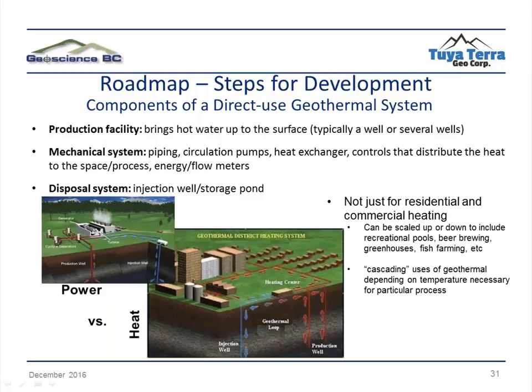And then you've got the disposal system. So where are you disposing that system? For the most part, injection wells are used in order to maintain the pressure of a geothermal resource, for example, and to minimize environmental impacts. You don't want to be necessarily storing the disposed fluids in a pond.